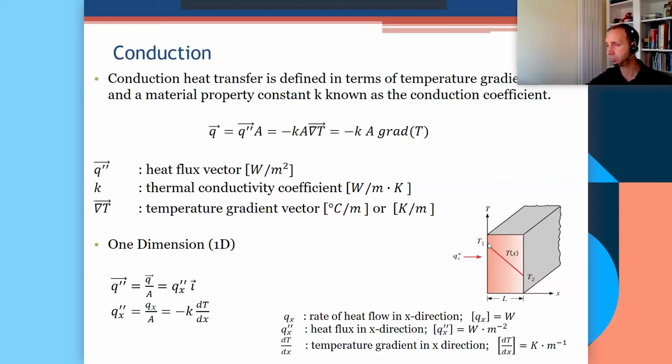You could travel along a slanted line, but essentially you would go through a slower gradient or slower rate of decrease in the temperature. We want to go in the direction of greatest decrease, and that's perpendicular to the wall. So that piece of information is captured within a mathematical operator called the gradient operator. If you apply the gradient operator to the temperature variable, then you get a vector, that is, a mathematical entity that carries both information of magnitude and direction.